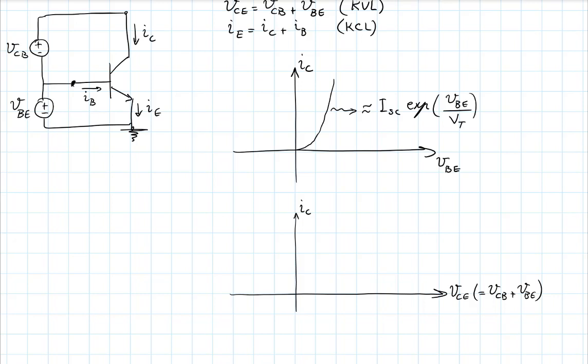This is a very important curve, so please look very closely. Imagine you have a transistor where you have applied a VBE of about 0.7 volts at the input. So you have turned on that diode. So your VBE is somewhere around 0.7 volts. Now you start increasing VCB so that the sum of the two, which is your VC, is a large voltage. It's maybe 2, 3, 5, 10, 20 volts. So I'm somewhere here on the axis, large values.